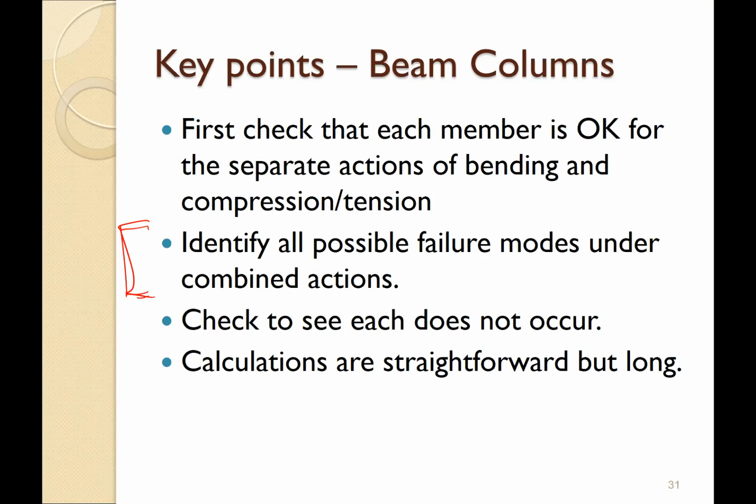And to remember it in a simple way, I will again give that summary. First, you start from the section capacity. If the section capacity fails, choose a different section, revise the section. Once the section capacity is satisfied, you go to the in-plane or out-of-plane check, depending on the requirement. Usually the steps people follow are section capacity, in-plane capacity, and then out-of-plane capacity, because it is obvious that if you consider out of plane, you will have the worst or minimum capacity, isn't it?